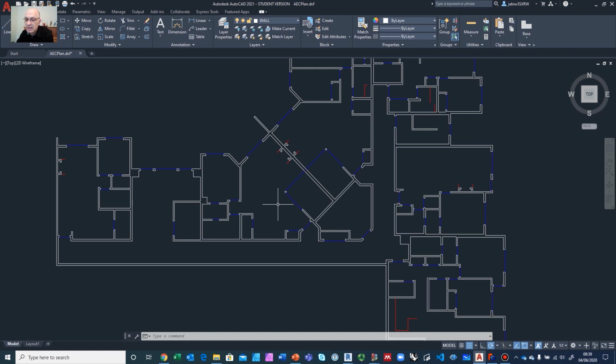First thing I have done is I replaced all the door swings and the pocket doors with just simple blue lines. And anybody who uses AutoCAD, I haven't used it in many years, it should be an easy task to replace all doors with just the single line for the width of the door. The reason for doing that is that if you leave the door swings, the arc of the door will be part of the shape of the room, and actually the inside of the door will be another room, another closed circuit. So you really don't want that, as well as the door leaf will be a different circuit. So you should just simply abstract it a little bit and put a boundary between rooms as a single blue line, as you see here.